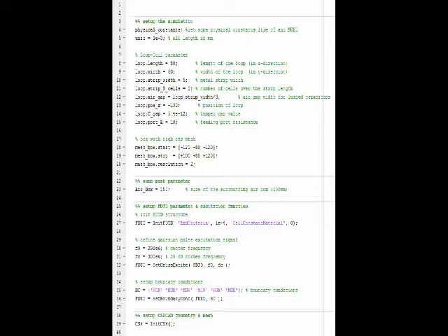The box has high resolution meshes. The mesh box is starting at negative 120, negative 80, negative 120, and the stopping point is positive 180, 120, and 120. It is the same as the body box we created later. The mesh box has a resolution of 2, and this parameter we will also use later.